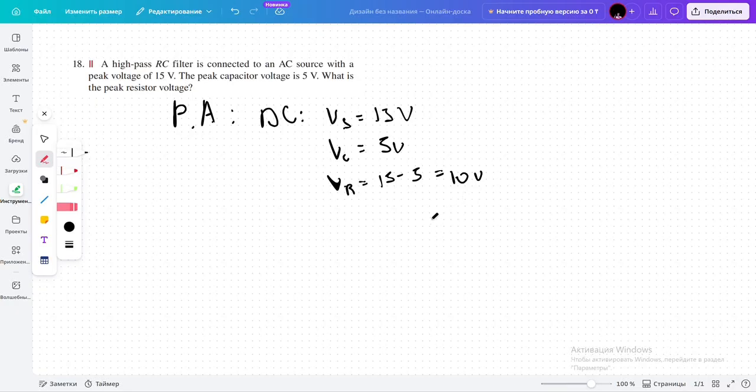But here I recognize a new pattern for AC circuits, because the current is alternating, the voltage across the capacitor and the resistor are out of phase by 90 degrees. The pattern here is a right angle triangle, meaning we must add voltage like vectors using the Pythagorean theorem and not regular numbers.